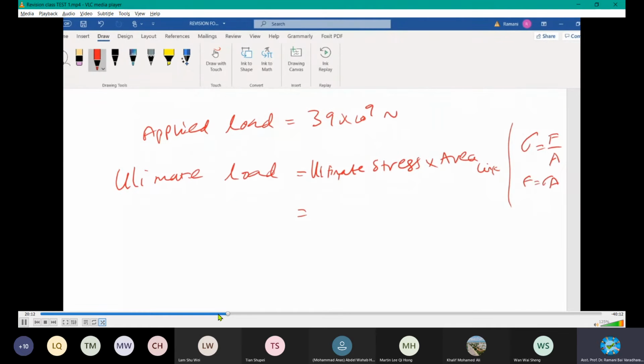Alright. How much is the area of the link? Let's find out area of the link. In this, the unknown is area of the link. Take the cross section. Just now we drew, right? The vertical cross section. I draw. Say got a pin, right? How much is pin dimension? 20, right? So the area of the link that is contributing to this will be this much, isn't it?